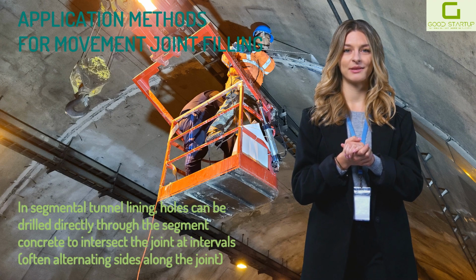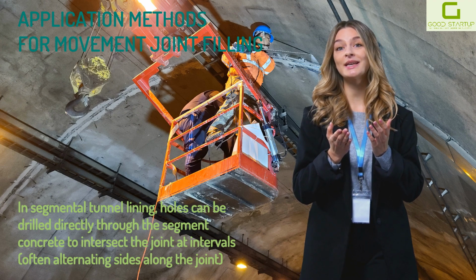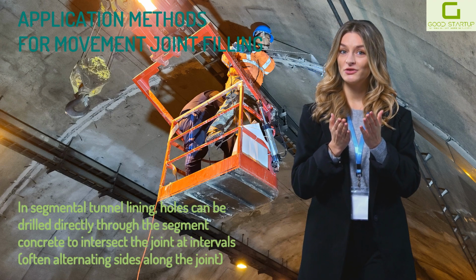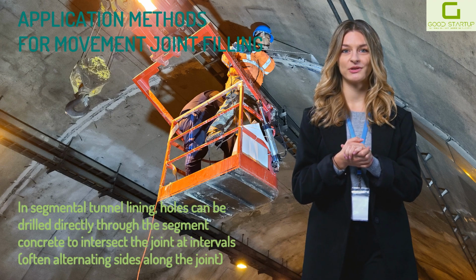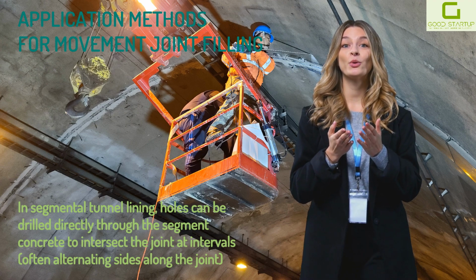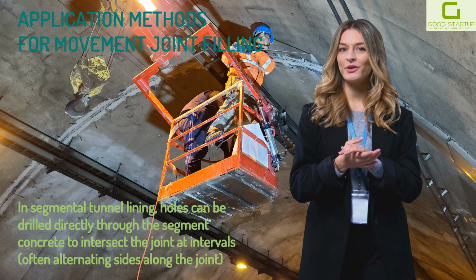For instance, in segmental tunnel lining, holes can be drilled directly through the segment concrete to intersect the joint at intervals, often alternating sides along the joint. Packers are installed in these holes, and a low-viscosity resin is injected into the joint area. It is crucial to use relatively low injection pressures in this process so as not to damage or dislodge any existing joint gasket or filler. The gasket itself often serves as a boundary to contain the injected grout. The goal is to fill the annular gap or any voids around the joint on the external, water-facing side, effectively creating a new water barrier.